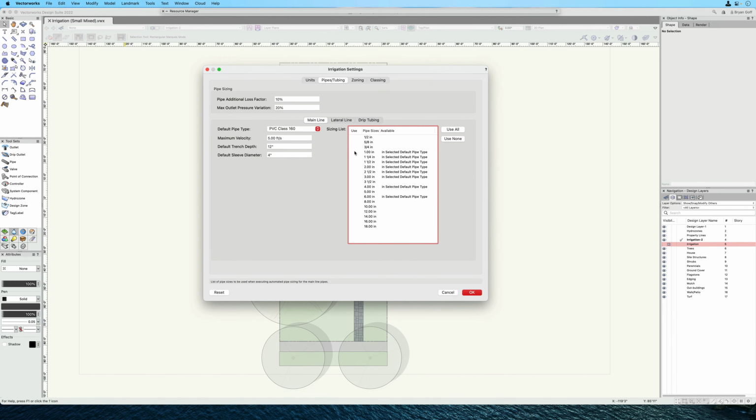And in this case, my mainline, I'll run mainline all the way to a 3-inch pipe, depending on the size of what I'm doing. I don't do a lot above that. So that would be key. Set these up. That means it automatically calculates the pipe within that range.